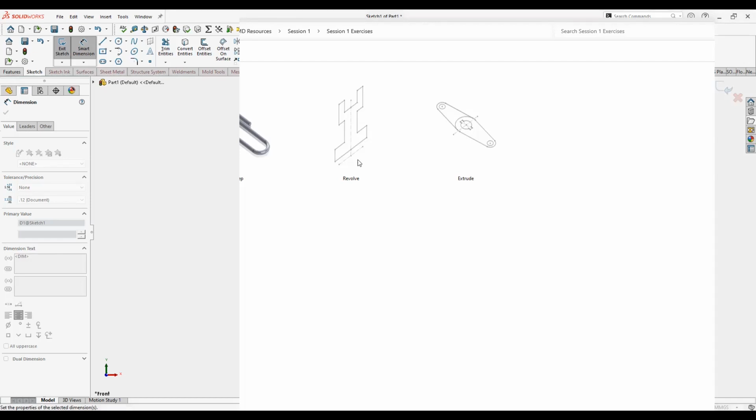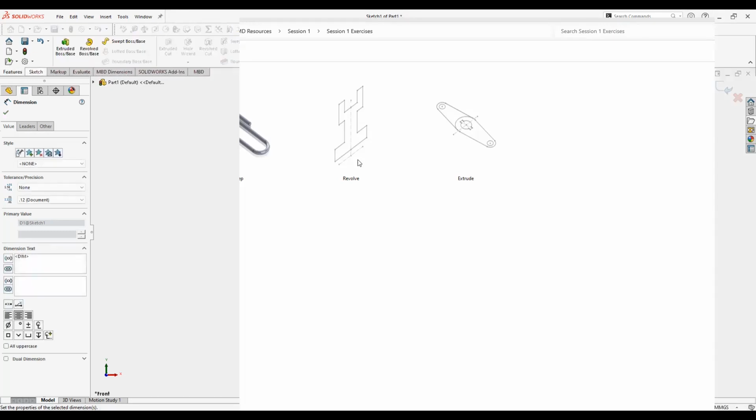And if you don't want this icon to appear, you can do the same as just now. Left mouse button, click, hold it, and drag it to any blank space. You will see this icon with a red cross beside it. Then you just release and the icon will be gone. So under customization, you can rearrange your graphical user interface any way you like. In this case, I'll just put it in the sketch tab over here. So afterwards, under sketch, you can see this equation.